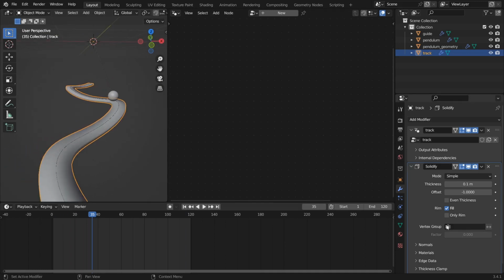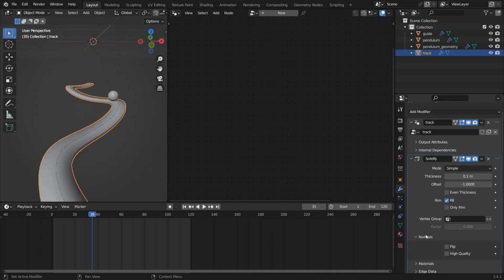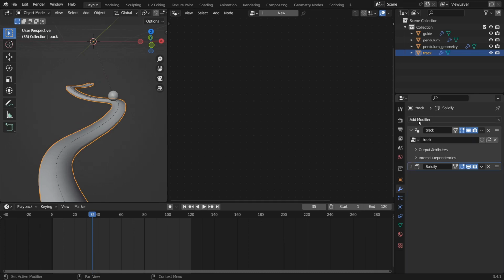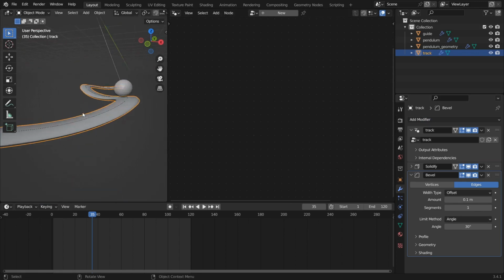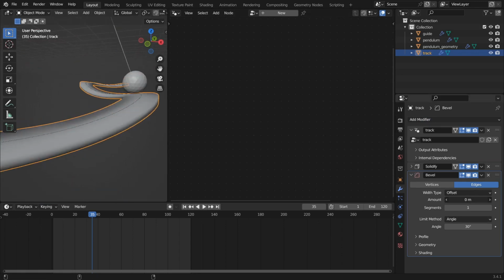One way that we can get rid of that is to add in a bevel modifier, which we'll want to use ultimately anyway, because it'll give a little bit of curve to the edge of our geometry. Set the amount to something really low, maybe 0.005, and that'll catch the light in our rendering and give you these nice sharp line edges.